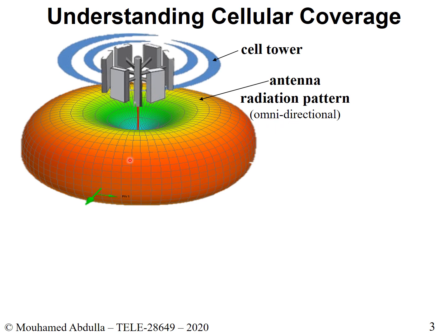Now, perhaps it's a bit lower here. I should have put it a bit higher, but that essentially gives you a sense of how the radiation of an omnidirectional antenna is. Here, the antennas may lead you to believe they are directional antennas in different directions, but let's consider it to be an omnidirectional antenna. It radiates in all directions. In fact, it doesn't radiate spherically, as we said with an isotropic antenna. Isotropic antennas do not exist in real life. This is just something that we use when we do analysis.